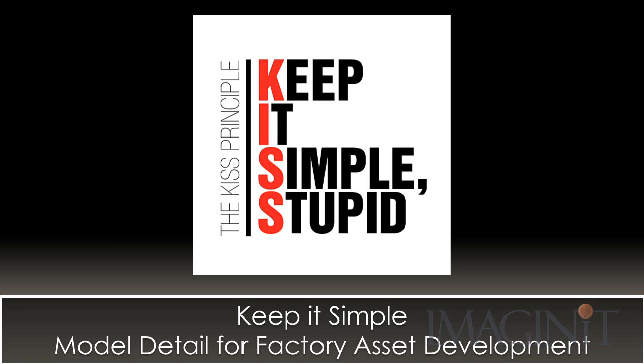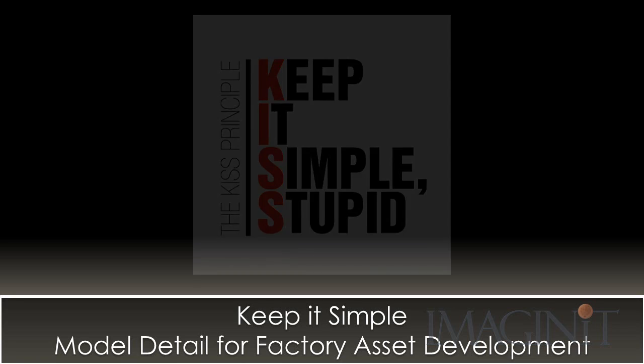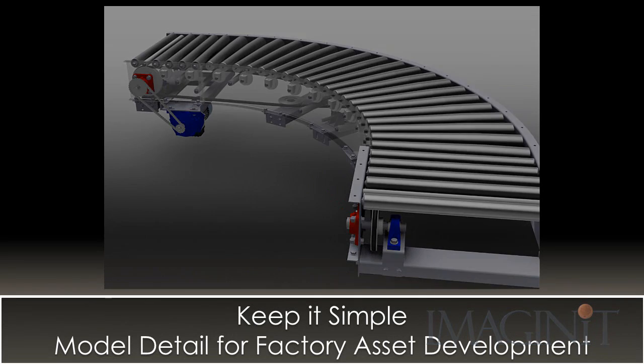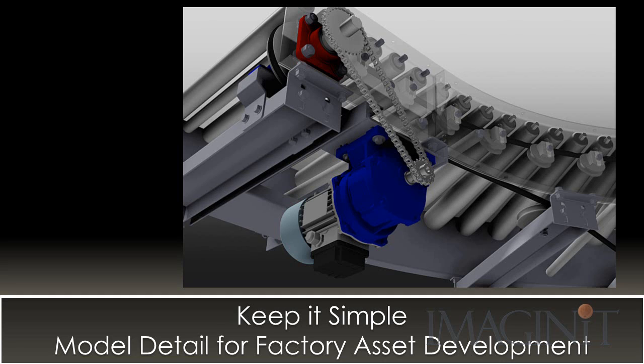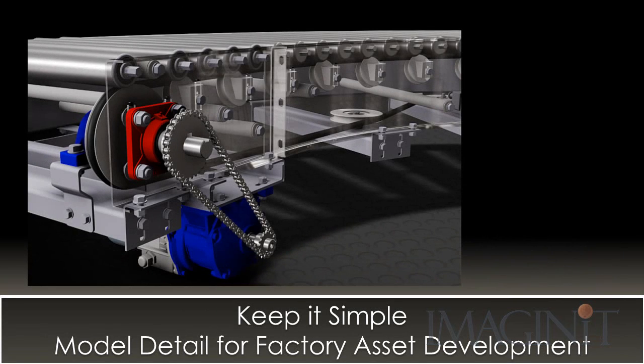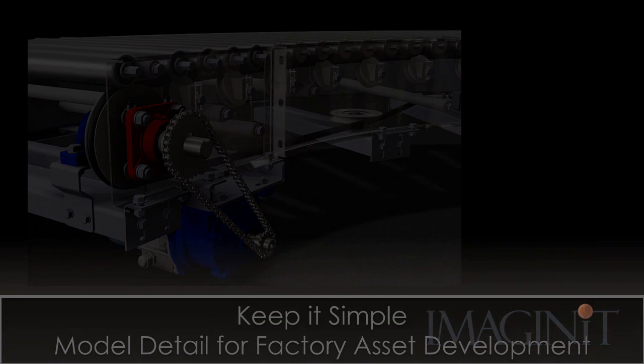I think most engineers are familiar with the KISS principle, keeping it simple whenever possible. And when it comes to asset development, this principle is extremely important. Very often, equipment manufacturers realize that their production level models are far too complex to use as assets in the Factory Design Suite. When they were generating the production level models, they included every fastener, every detail on the motor mounts, and the pulleys that make up their conveyors. And all of that detail is far too much to add to an asset model inside of Factory Design Suite.